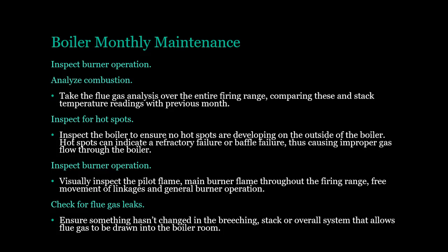Inspect burner operation. Visually inspect the pilot flame, main burner flame throughout the firing range, free movement of linkages and general burner operation. Check for flue gas leaks. Ensure something hasn't changed in the breaching, stack or overall system that allows flue gas to be drawn into the boiler room.